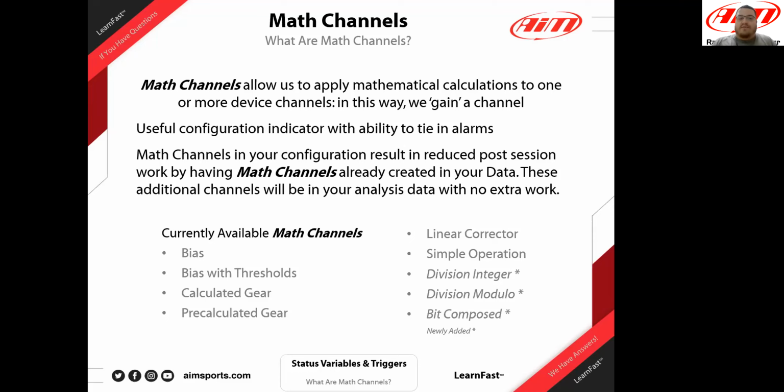This is what I say when I say gain a channel. So if you have 2 things that you might want to do a bias of, braking is a huge one for that. We have bias thresholds, obviously calculated, pre-calculated gear, probably the number 1 and number 2 math channels we use.